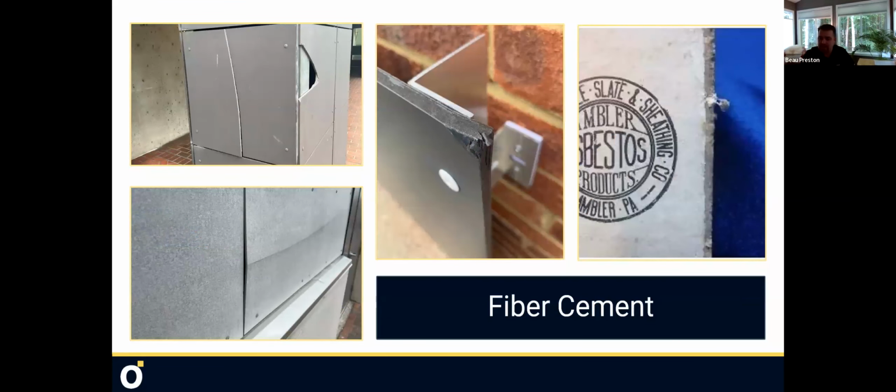Going to fiber cements, this is what you see when you look at 5 and 10-year-old fiber cement projects. You're seeing cracks, whereas it feels real tough. It feels strong. You have 2 pieces in your hand, and I think Victor wanted to know a little bit more about this. One has Portland-based cement and some fiber, and it's a Hatschek machine. I can get deep into those weeds if you'd like to, Victor. I'd love to have that conversation with you, but they snap. Break one over your knee, break it on the ground, drop it.